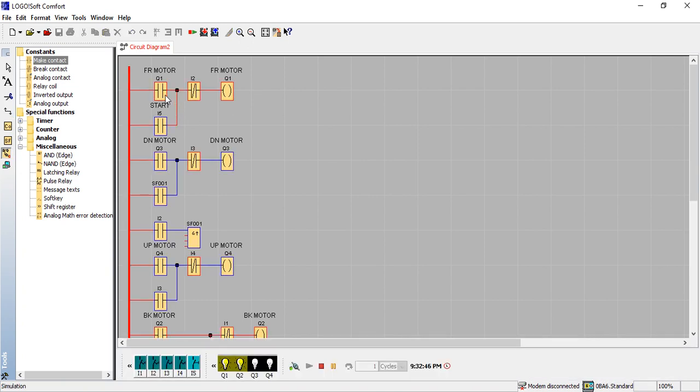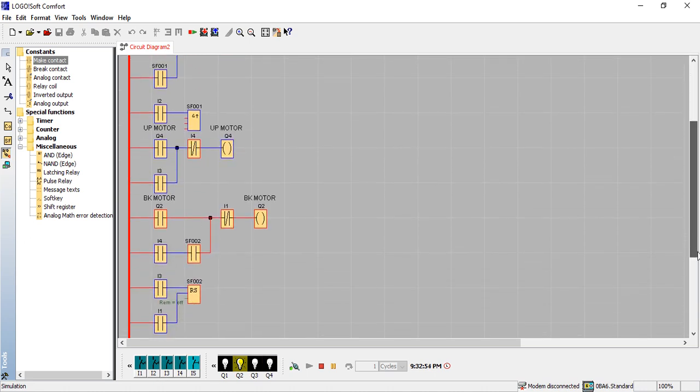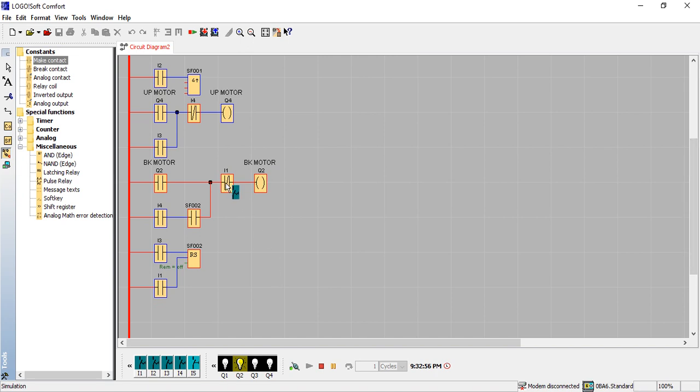Okay, switch off anything that you don't really need for now. As a matter of fact, I4 is currently on alone. So this is I4 is on. Look at now, I4 is no longer able to switch on the backward motion. You see now we have an end here that will be activated by I3.